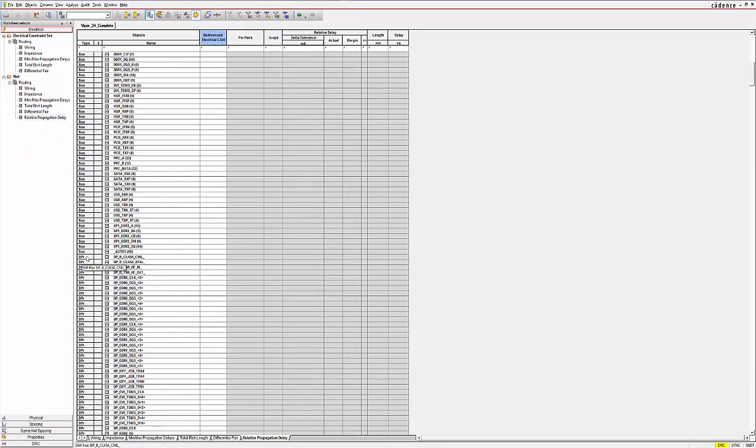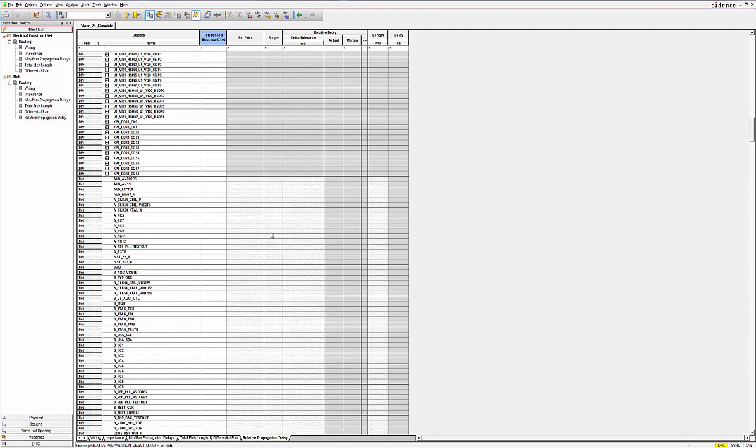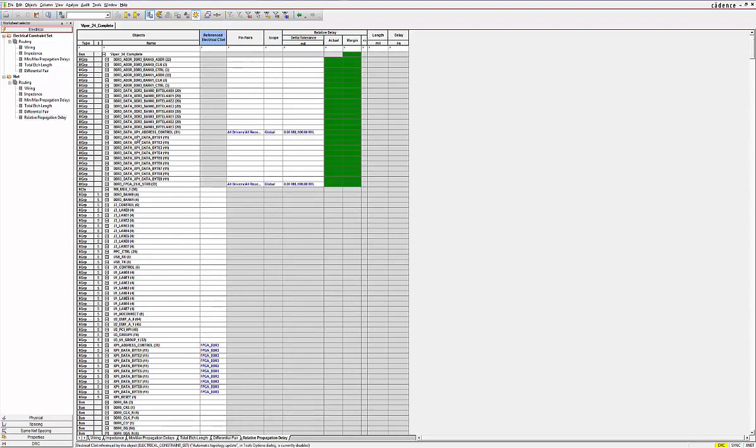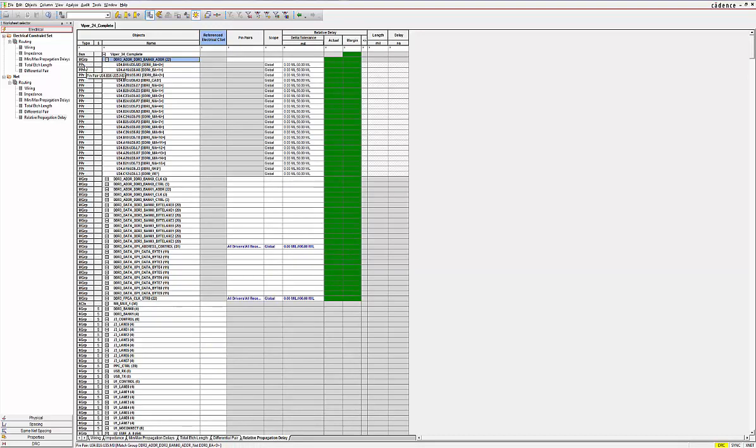Additional to error markers in the PCB design, visual indicators are also provided in Constraint Manager if rules are met or are in conflict. Red cells indicate that a signal is not routed within the length allowed, and green indicates that all signals meet the rules.